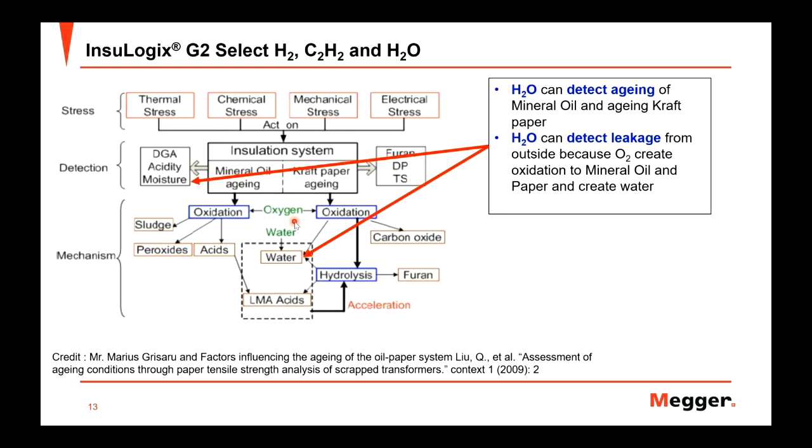And also the water inside your transformer is the main factor to accelerate the aging of your installation. That means you have to monitor water, otherwise something may happen inside your transformer and the aging of your transformer starts to increase in a tremendous trend. You can do a drying process or many things to take the water out of your transformer.